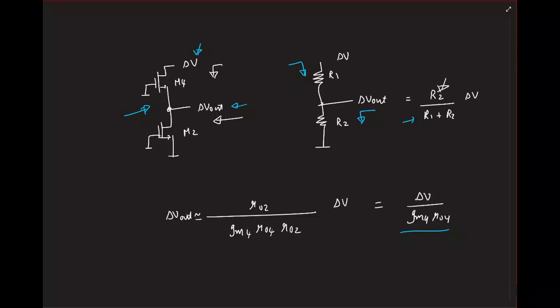Cool. So let's get back to where we were in the last class. We basically tried to use this cascode and increase the output resistance. So we had the PMOS current source, PMOS cascode, NMOS cascode, and the NMOS GM, and you had a copy here.